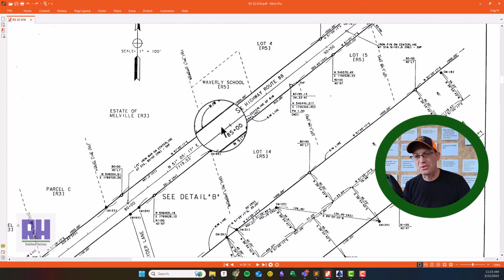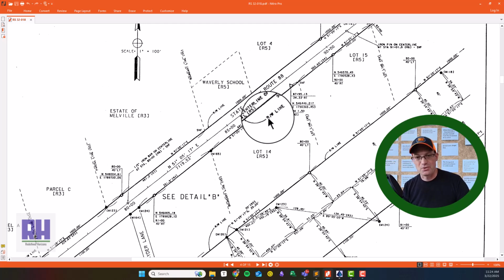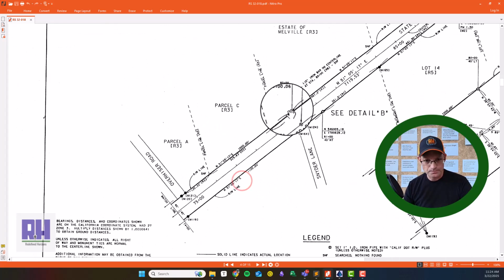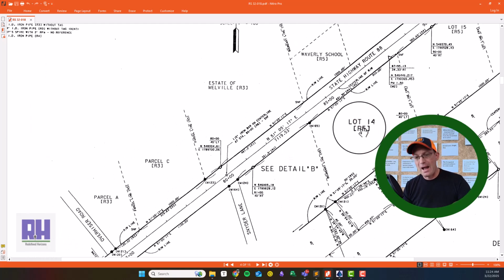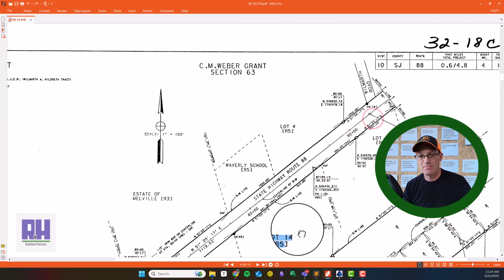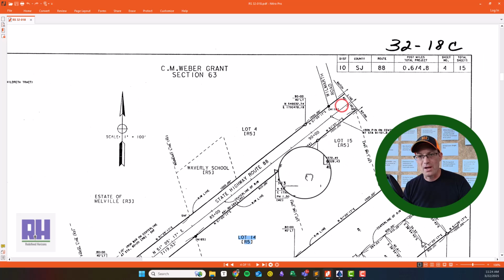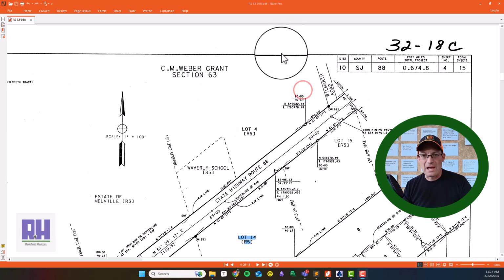Highway 88 I'm sure is ancient. It runs up from Stockton to Jackson. It was probably a wagon trail back in the day. So it doesn't have clear title like most modern highways. Newer highways are going to have clear title and right-of-way. This probably does not. Looks like Caltrans is asserting an 80-foot wide right-of-way here. They probably do not have deeds for that. But we're gonna roll with that for now.